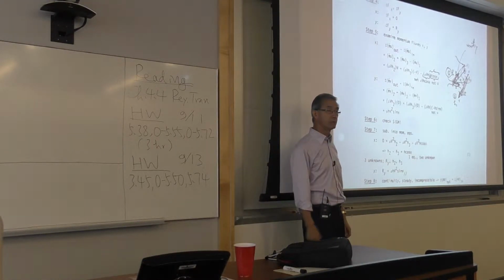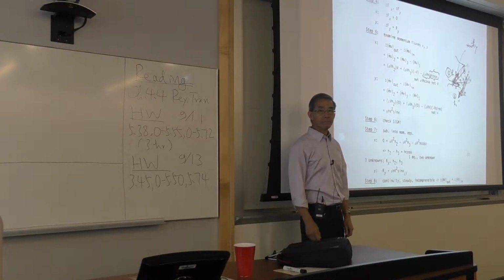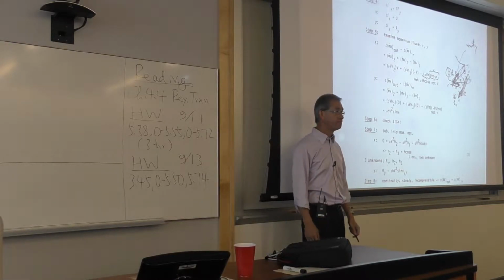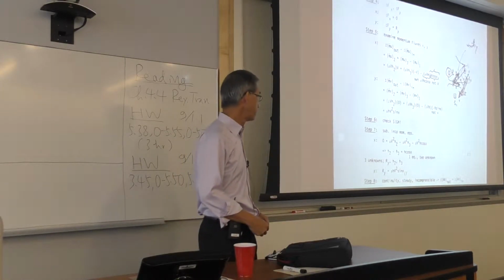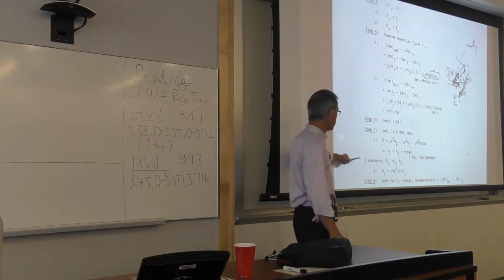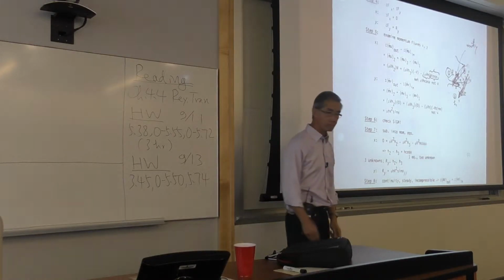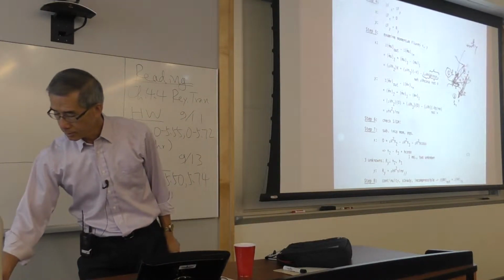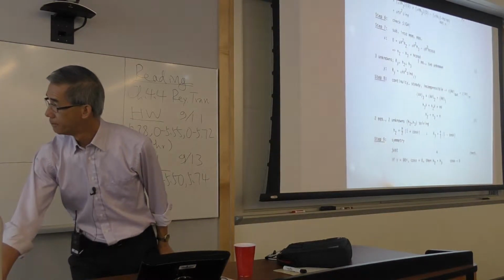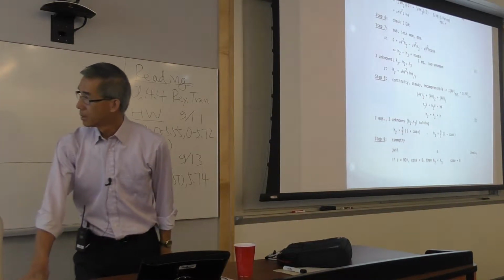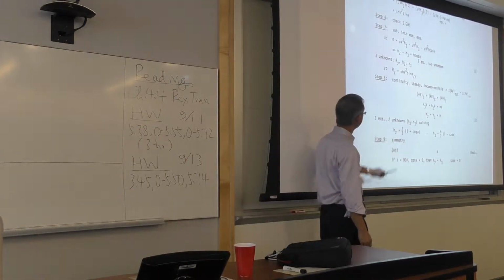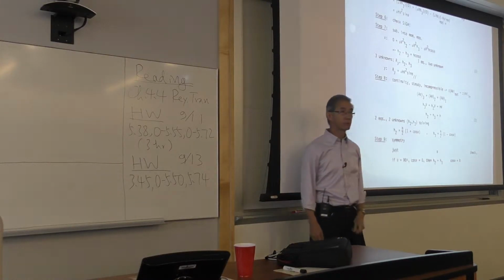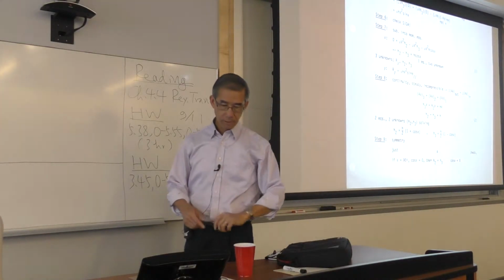I'm using 1 equation to solve for the 3rd unknown. What haven't I used yet? What haven't I put down? Continuity. And if you do that using continuity, and you should check also with the 3rd equation of continuity, the problem is solved. And the answer is at the bottom for H2 and H3, as well as Ry. And you can check symmetry to see if your answer is physical and correct.